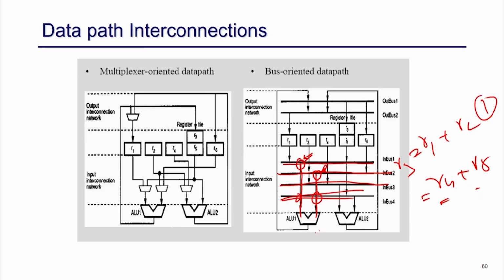So, this is the bus based data path, and the mux based one we discussed in the last lecture. We put a mux at the input of the FUs and at the input of the registers, and then we add control signals so that I can control the data flow, this versus this, based on the operation going to execute in that particular time step. So, both are possible and both are kind of the same. Here a switch is nothing but a 2:1 mux. So, both are possible and we can generate any of them.